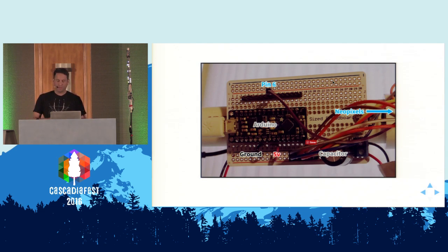And if you haven't worked with hardware before, the lines here are actually all bussed together. So that's why you see all of these wires here, because this is distributing power in multiple places onto the strip. It's usually a good idea just to do that so that you're not just relying on a single wire delivering power to the entire strip.